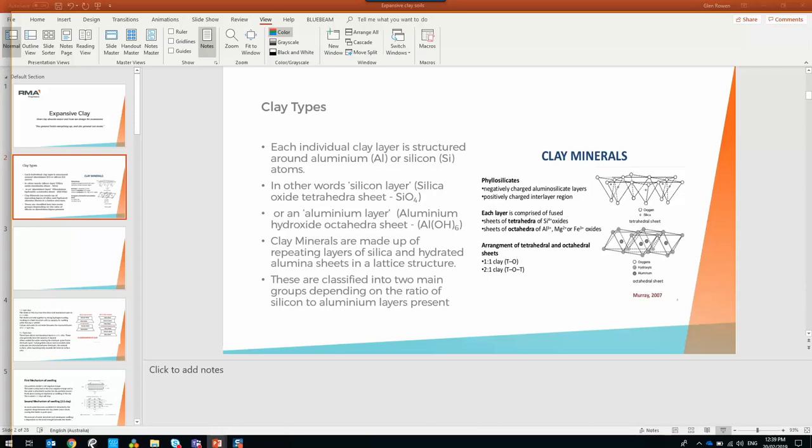It's a bit small scale, but typically this is a residential job we've done. And you can see the pier up the top there. Basically what we're trying to do is not have any of the structure touching the top 1.5 metres of the clay. So we put an overbore, a former tube liner and a gravel backfill around the clay, so the clay can't grab the pier and pull it out. Because if you just do a 5 metre deep pier and you don't do that, the clay will just grab the pier and snap it. So it's very important that you do that.